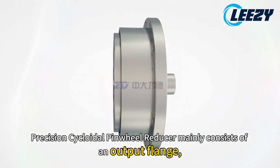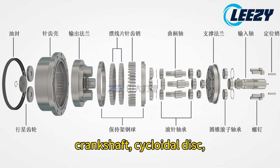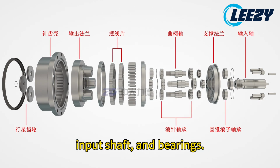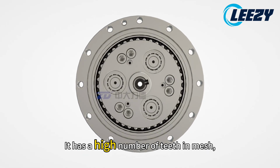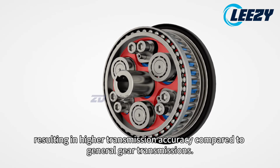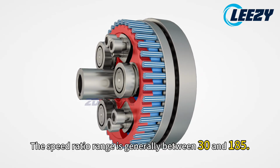The precision cycloidal pinwheel reducer mainly consists of an output flange, crankshaft, cycloidal disc, input flange, pin gear housing, planetary gear, input shaft, and bearings. It has a high number of teeth in mesh, resulting in higher transmission accuracy compared to general gear transmissions. The speed ratio range is generally between 30 and 185.